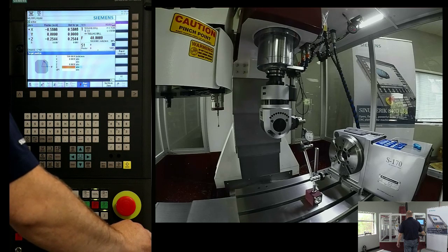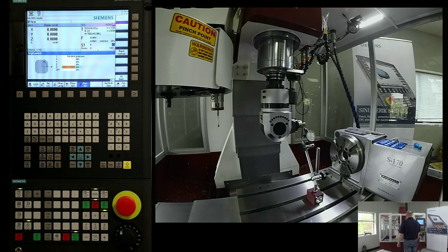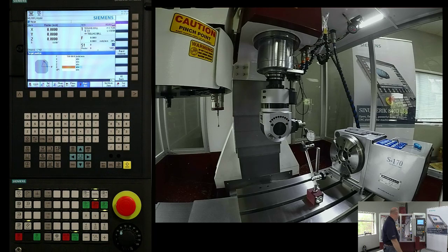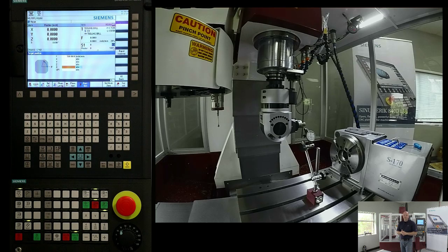So always remember, you're going to work from the center of the ball. There we see, I don't know, maybe 4 tenths over. That's pretty good. Certainly, I have to keep in mind the positioning accuracy I should expect with this type of setup. But I would say if you can stay within a thou or so, that's doing really good in this scenario. And then if you wanted to, you can get much more accurate methods. So this is basically the initial setup for getting it to work.